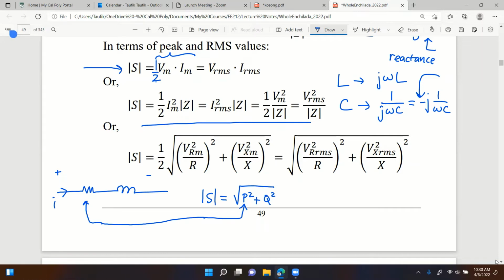Because it's imaginary power, yes, exactly. Because P of L is equal to, what is it? What is the average power of an inductor? You must know this. 0, yes. And that's why the only average power you get from this simple circuit is from R.